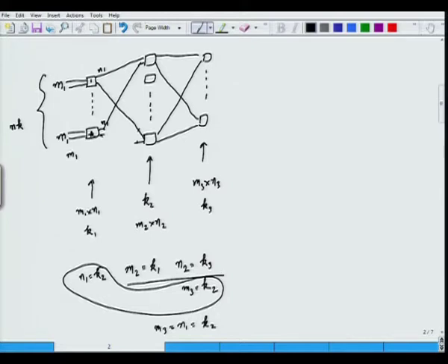And I said this switch can actually become strictly non-blocking, and I took a very simple example. This will be later proved as a Clos network. This is actually the Clos network. We will use the Clos theorem to find out what will be the condition for strictly non-blocking nature of this particular switch. So, if M1 minus 1 lines are already busy occupied here,